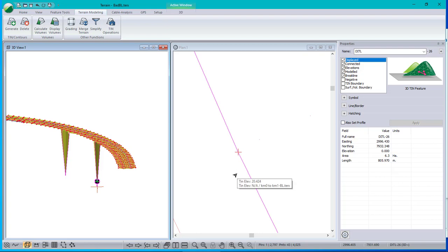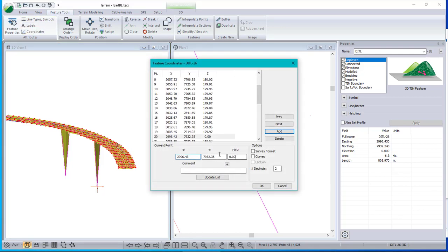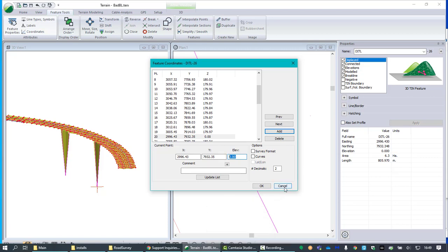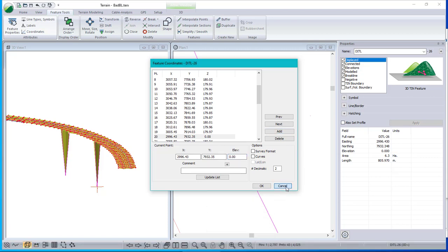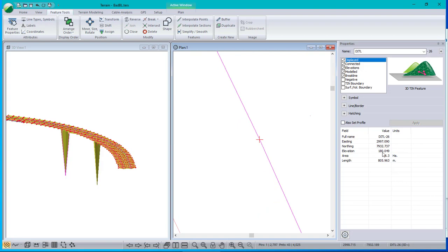0. I can change the elevation manually in the coordinates dialog box. I could literally type an elevation in there and change the surveyor's point. The other thing I could do would be to find another point that looks right. How about this one? See, that's at elevation 180. I think that's the point that should have been the ditch line. So what I'm going to do is select the ditch line, edit this point, there it's captured, and snap it onto that point. It now has a reasonable elevation, and I fixed problem number 1.